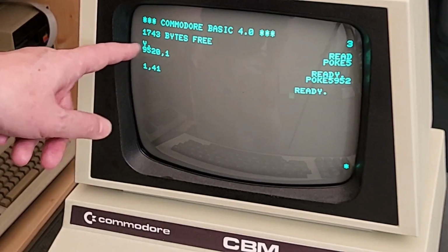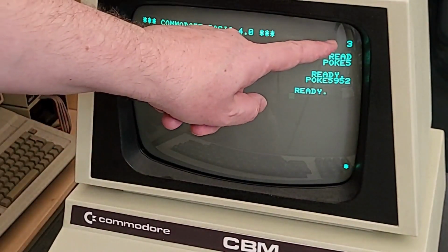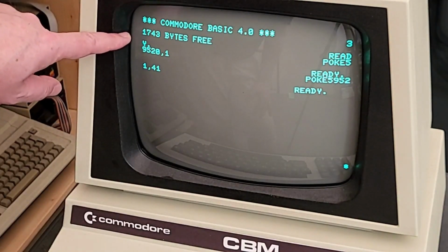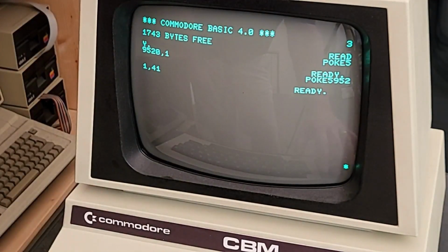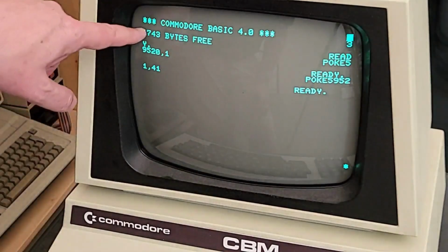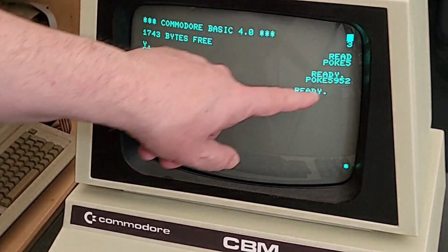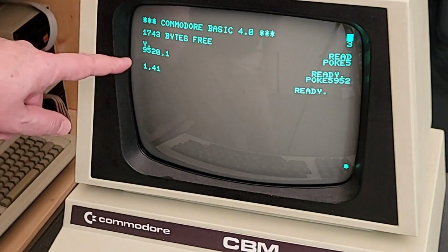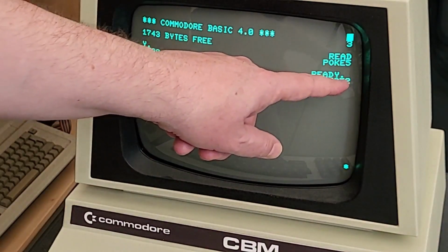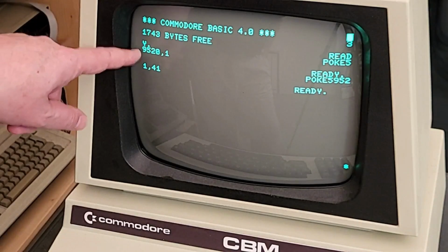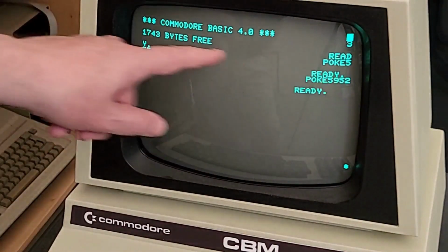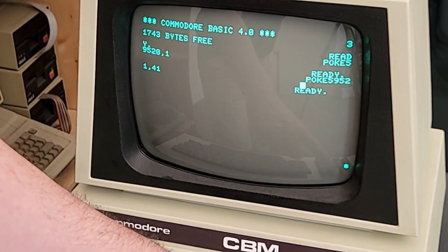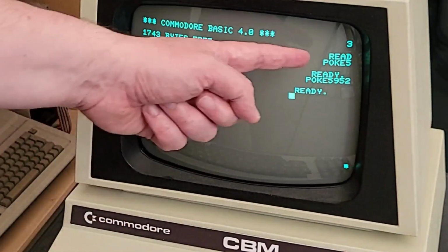So what you see here is in the first character line, there's one character more that is being displayed, and it's taken from the next character line. Actually, this is not the very first one, because that's the second one. So this is coming from the bytes 3 value and so on. And every raster line is now 41 bytes. And the CRTC reads 41 bytes from memory. And the next line starts 41 bytes further, and not 40 like it is normally. The kernel does not know about this, so it's just doing its thing as if there were only 40 characters.